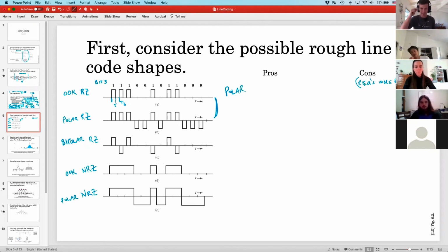So I'd go one beyond just thinking of minimizing power required and think about, you're not actually here to minimize power, you're here to get bits from A to B. And so we should actually be thinking of this in terms of which one requires the least power for the same error rate? Or for a given power, which one has a better error rate?